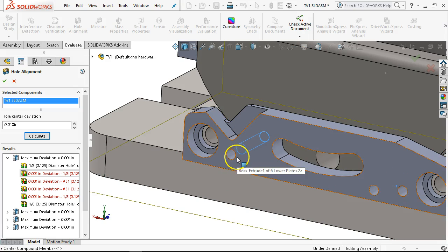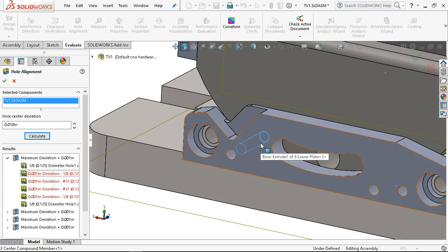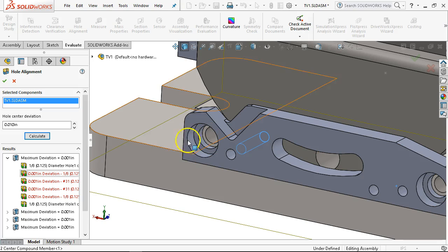All right, if I hit those numbers. Otherwise we're back to the original notes of, well, I need to assemble this and then set the whole assembly up in a mill and drill and ream this and press the pin in at the same time. That to me is kind of counter to the manufacturing process. I should be able to come up with a positional tolerance for the size of this hole, the size of the ream, press the pin in, slide this over the top of it, and positionally this will be within a thou. A couple thou at most.